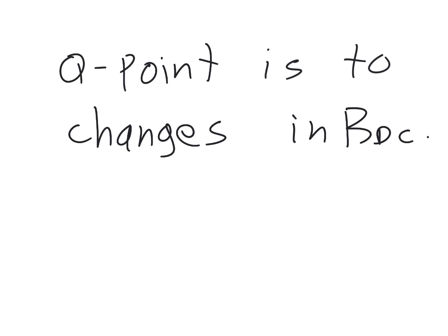We used to do a lab, and the students no longer have them, so it's kind of impractical. They had a soldering iron, and you just heat up the transistor with the soldering iron for a bit, and then you would note the change in the voltage and the current.